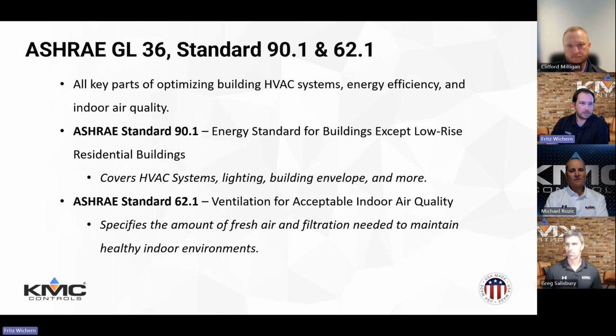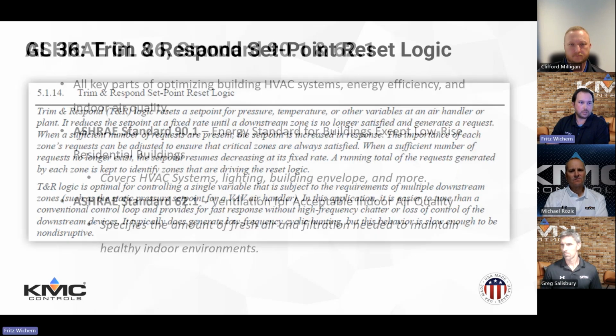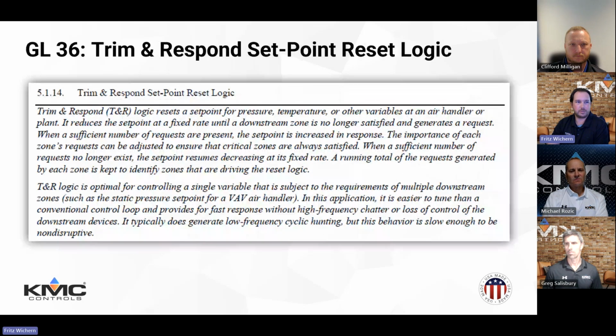So we got that out of the way. We're going to look at some examples of some basic control programs for the different pieces of the trim and respond set point logic that you see in Guideline 36, in section 5.1.14, our set point reset logic.